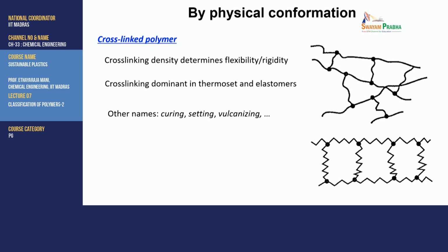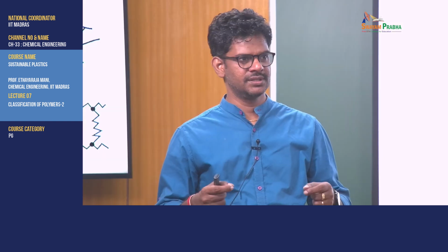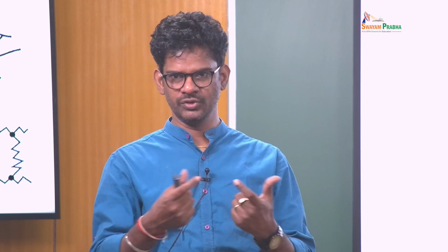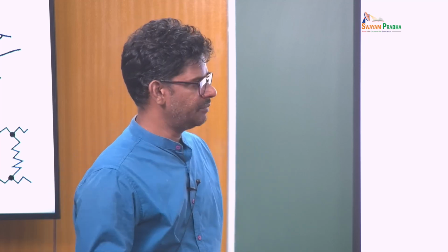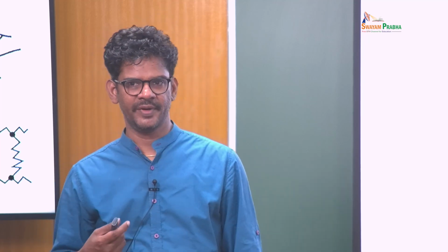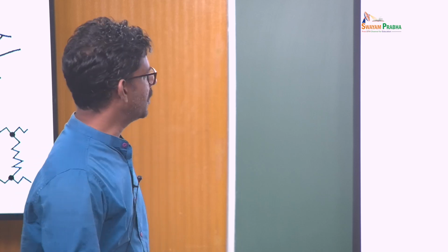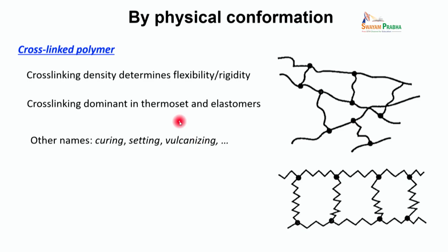Then we have a set of cross-linking. We already mentioned cross-linking, which means that there is a chemical bond between the side chains that holds the molecules together, and the cross-linking bonds are as tough, as strong as the main backbone chain itself, right. And many of the thermosets are made up of cross-linked polymers. So, now when we think about cross-linking, we also say something called cross-linking density.